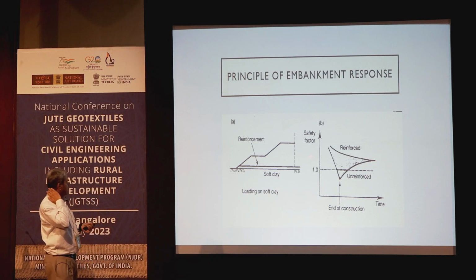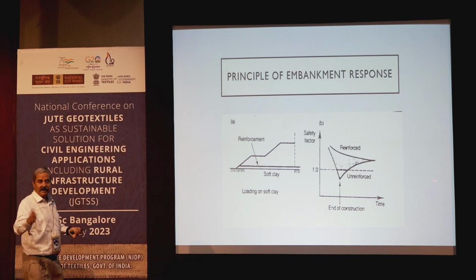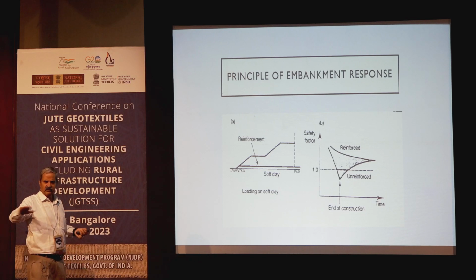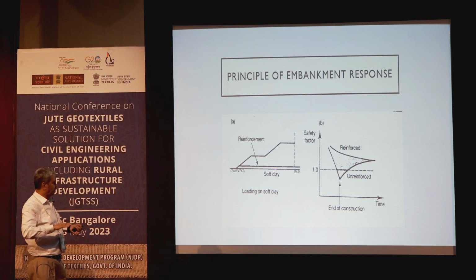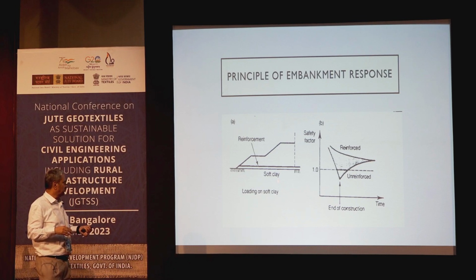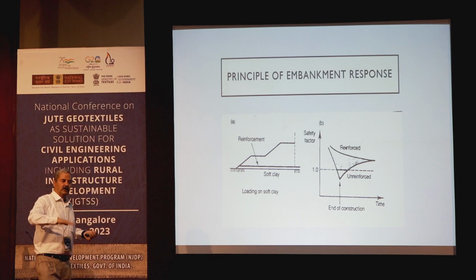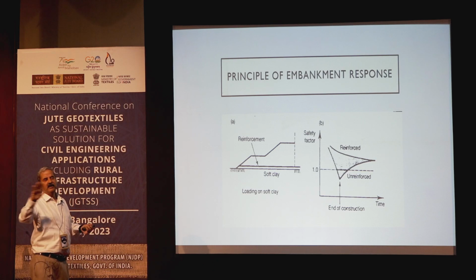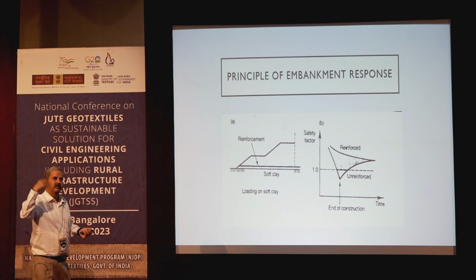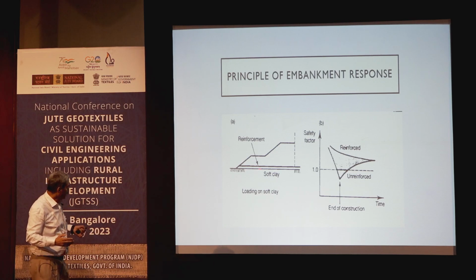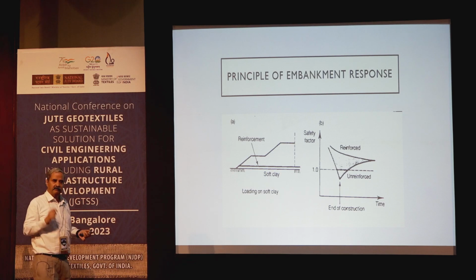This is another important thing. When you're trying to construct an embankment in a soft soil, right? You can't even walk, right? In some places, you have to put a loading platform and all that. What we do in normal practice in the soft soil is what is called a stage construction. Stage construction means you allow some load and then wait for some time. So consolidation takes place, pore pressures completely dissipate. Then you again, maybe 2 meters again you fill it up, 3 meters you fill up. So you go on constructing like this, but it takes time.